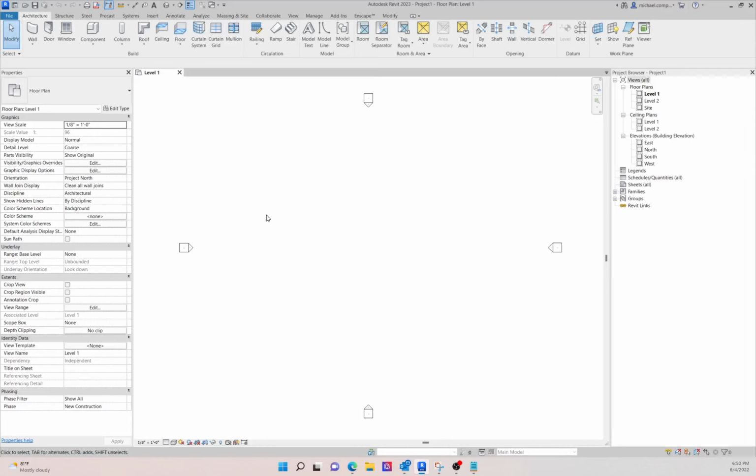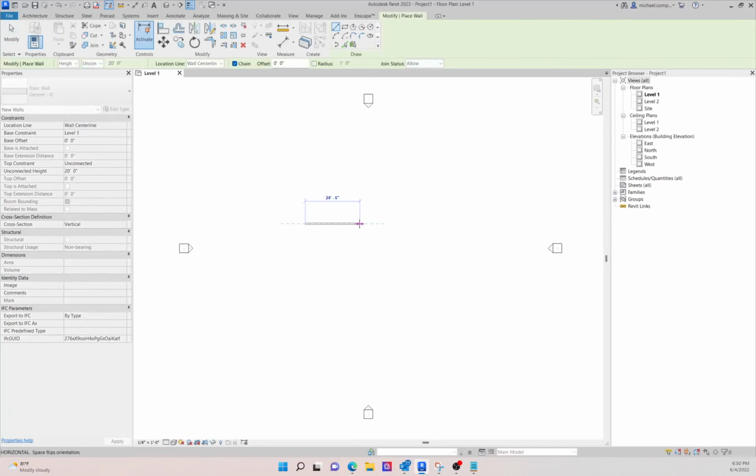But you can create it at a scale, meaning, so if I draw something in here, let's say a wall, and I want that wall to be 30 feet, I click once, drag out, type in 30 feet, enter, and it's 30 feet. I'm not having to do math in my head. This scale is what it would be if I were to print it at scale. Same thing is true with text and all that stuff. So I'll get into that. I'm getting ahead of myself.